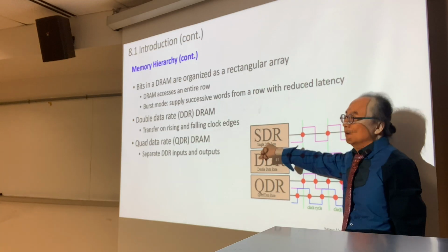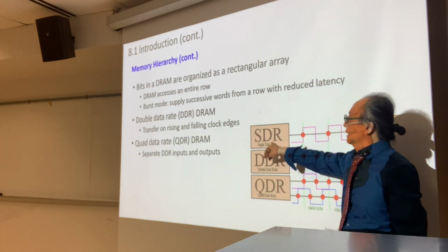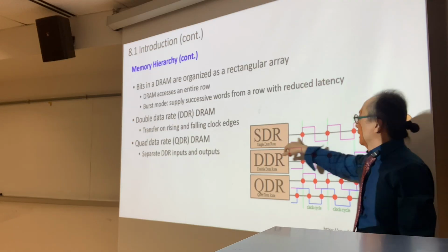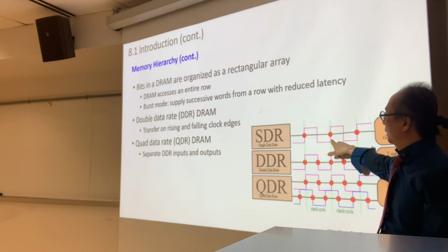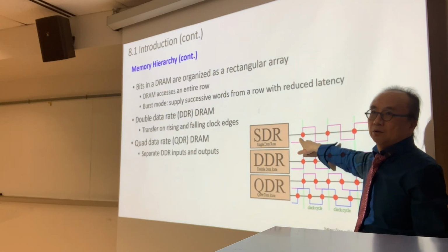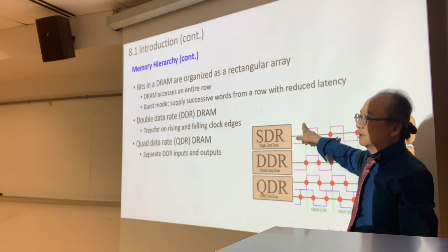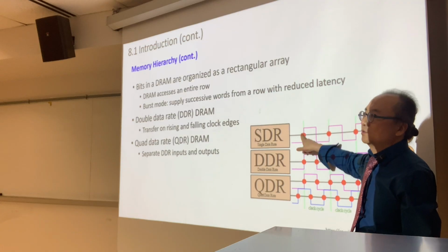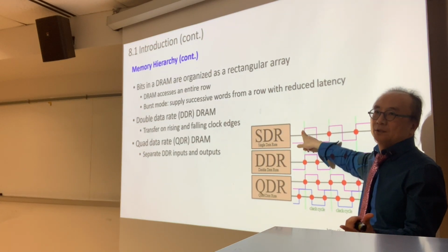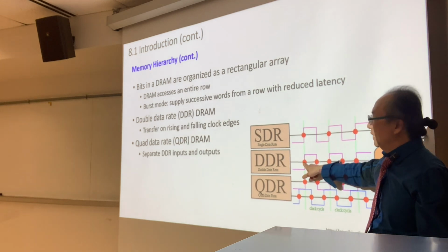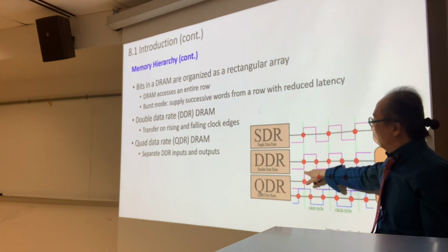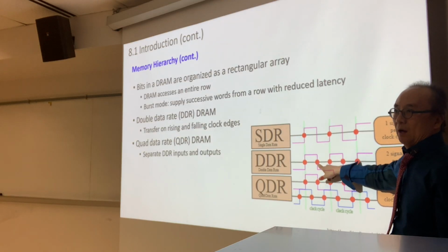In a typical clock cycle, which is single data rate, anytime the clock goes up, we're going to write or read. The only thing we can do is on the positive clock edge, whenever the clock goes up, we take one action. However, in that pipelining, we can write before we read within a single cycle of the clock.